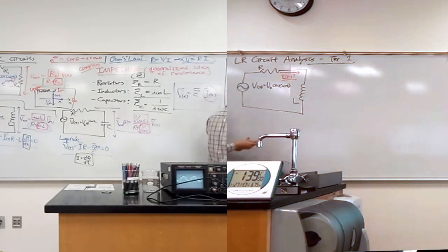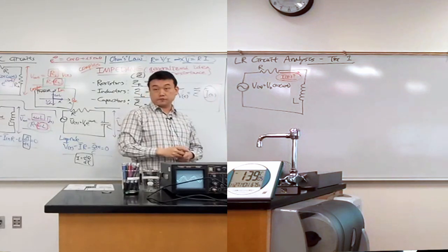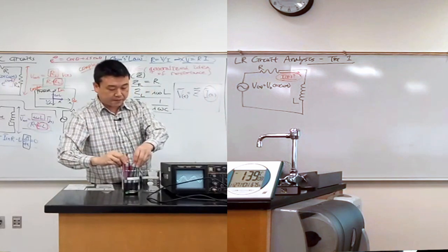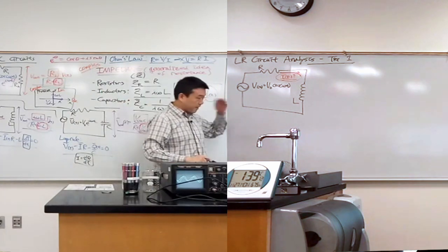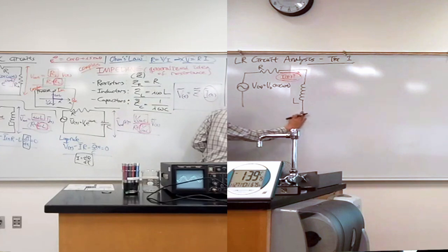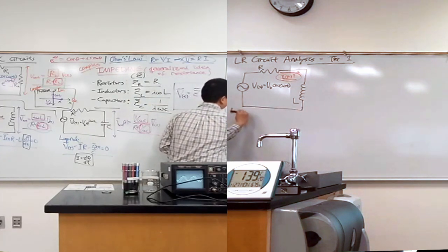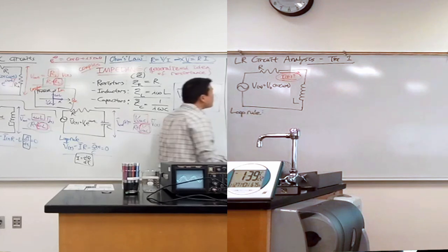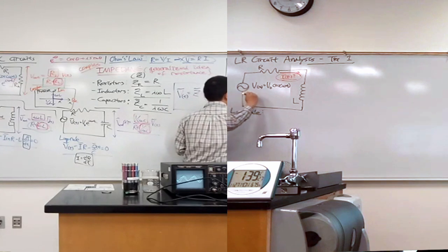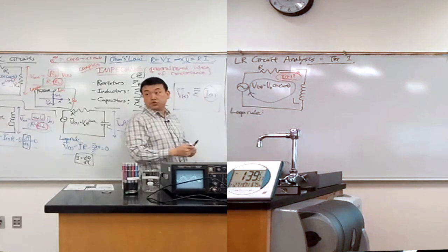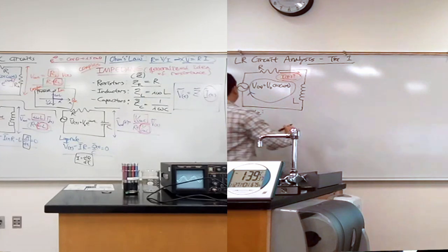What is the current as a function of time? So this is where we do have to use Kirchhoff's rules. So let me just set it up, and I mean, you've seen this multiple times, but let me just set it up so that I'm not leaving anyone completely behind. So Kirchhoff's loop rule says that when you go around in a loop, collecting all the changes of voltage, then the voltage change should add up to 0.